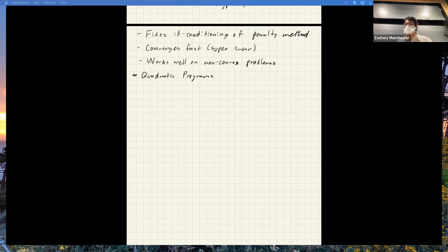Now we're going to look at quadratic programs. These are super, super useful. This is currently how MPC is done on most legged robots, and on autonomous cars. They're used all over the place. One reason is you can solve these super fast. You can write solvers that achieve kilohertz or faster rates, so you can run them online in a loop and get a stabilizing controller out of it. What this looks like is minimizing a quadratic function, specifically a convex quadratic function.